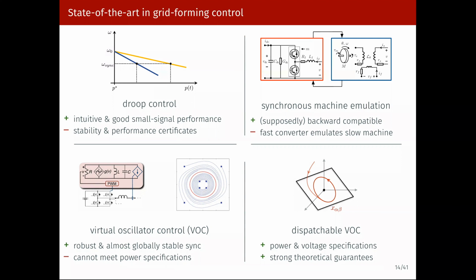I see. And just another follow-up. So with power converters, I'm assuming they're mostly interfaced with renewables, right? So when you're looking at the real-time operation of the grid, the share of renewables is changing over time, right? So would this control still be working even when the renewables aren't producing any? No, exactly. With the controls I'm showing you here, it will all fail miserably unless you put a battery on each and every one of these converters. Once we are past this, I will show you a control that addresses that problem. Okay, thank you. Sure, thanks.